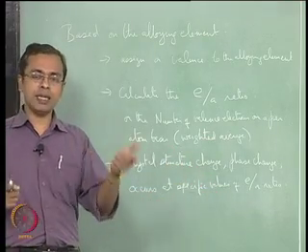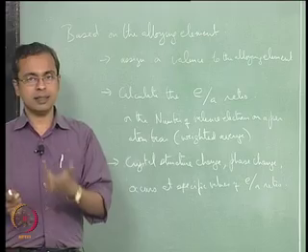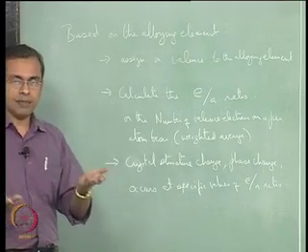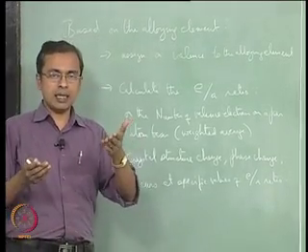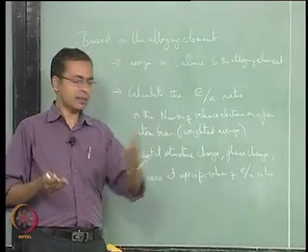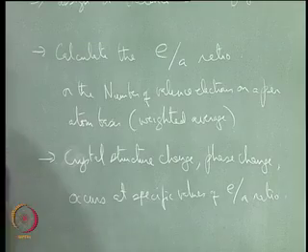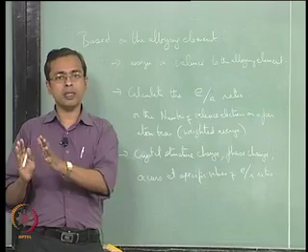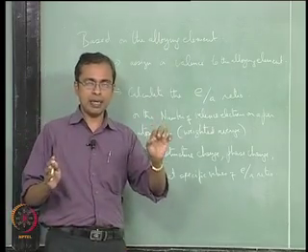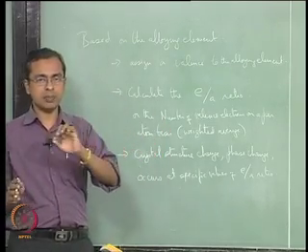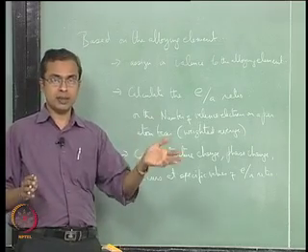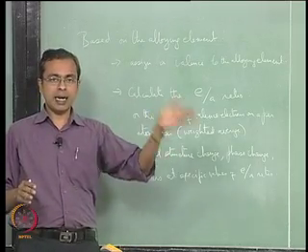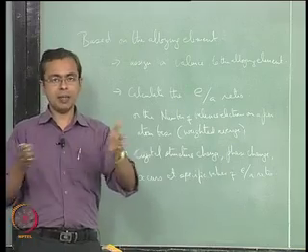That is simply because the valency of that atom that you are adding is different, okay. So the valency is different, and so you may have to add more of one atom to get the same E by A ratio relative to some other atom. Given that you are starting with copper, if you add one alloying element which has some valency as opposed to another alloying element which has twice that valency, obviously you have to add half as much of the second alloying element to get the same E by A ratio, right.